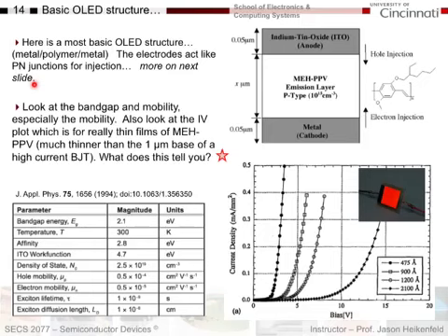Okay? So here's your emission layer, there's the molecule, and then I've got these two electrodes which inject electrons or holes. So looking at this device, here it is emitting red light. There's a couple interesting things. Look at the table here. Here's the band gap energy, 2.1 electron volts, which is for red light. That makes sense.